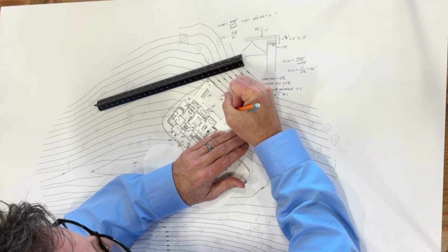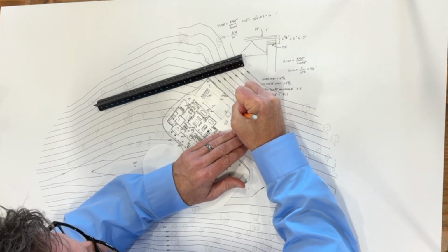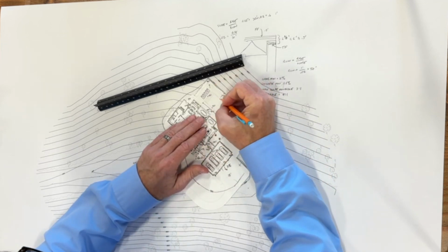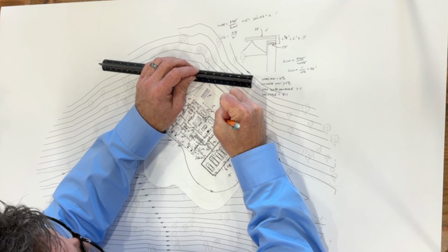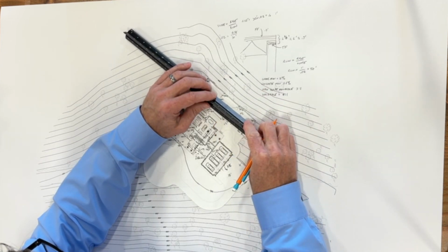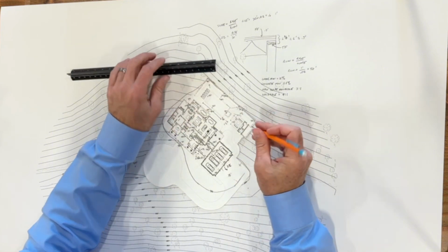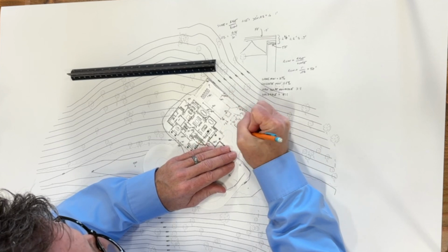So now we know a drop of water that lands there, if this is at 940, is going to make it at 2% going this way. So it's kind of water going that way, and it's going to go this way. And this is a 941 at the corner here. And we're less than that. Yeah, we're less than 50. So this could be a 940 over here too. So water can go this way. We'll make it a 940.